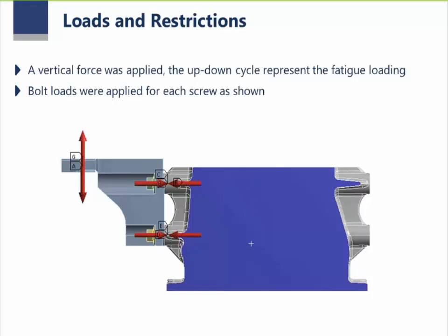So this is the condition for the fatigue loads. As it's a real model from a customer we have, there is a validation of this model. They go to the lab and test this part in 3 directions. For example, the most critical direction for this component most of the time is the up-down force, like we see here.